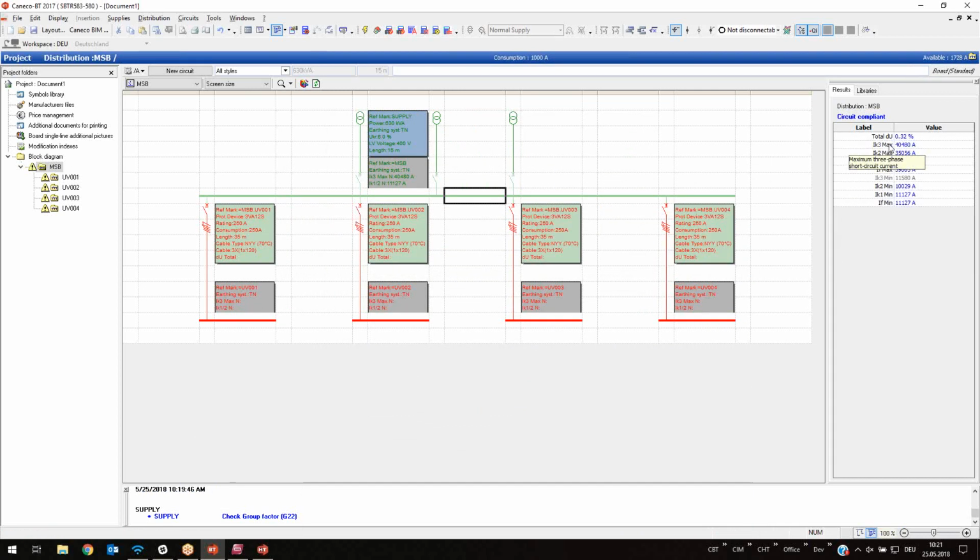Okay, please just repeat the last. No problem. Short circuit, yes. The minimum values are from 1 trafo, 11,000 or 10,000 ampere. And the maximum short circuit current, 40,000 ampere, is from all 3 trafos here.